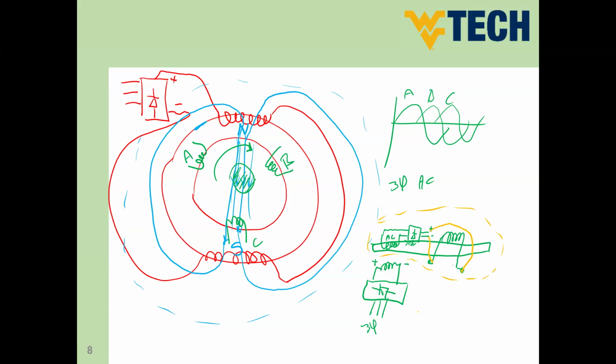And then the three-phase windings of the generator on the stator side will be receiving the flux coming from the rotor windings in order to generate the AC. So this is, guys, the concept of having brushless excitation. So we could supply the DC source to the field winding without having brushes in this case. But this is with the help of another machine, which is called the exciter.